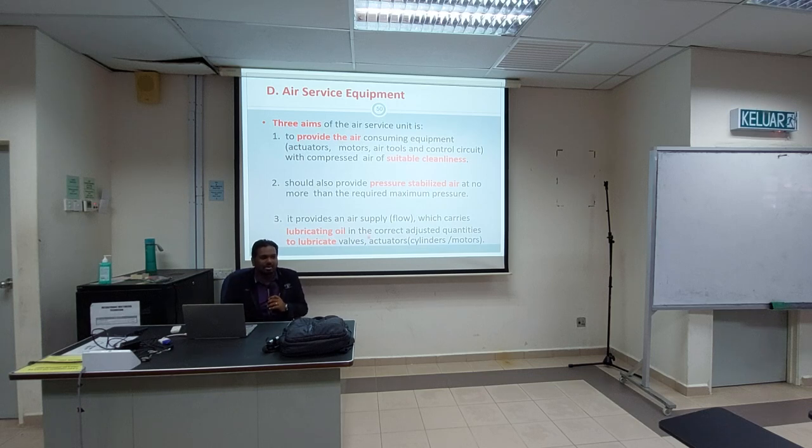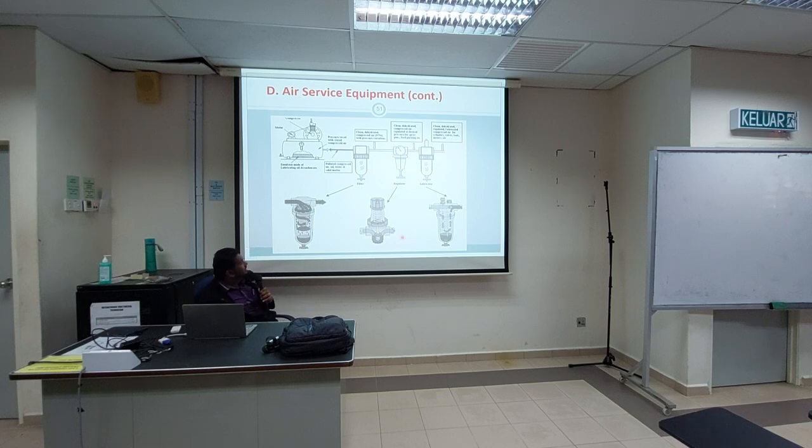Kadang-kadang perlukan lubrication sebab pneumatic is fully on the compressed air, so it's using air. So you need to introduce a little oil so that it can lubricate the valve and also actuator for your long run lah. Okay, so this is something that you can see in the lab later. Memang ada benda ni. So ada filter, regulator and also lubricator.